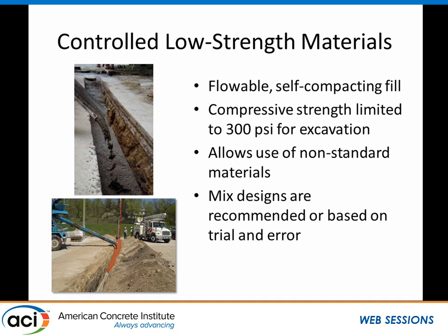And when you're trying to do this, oddly enough, the main objective is to get target strengths that are really pretty low. In fact, that's one of the hardest challenges, to keep your strengths down around 300 psi. I'm not just missing a zero there, 300 psi. And the reason you want that is to make the material excavatable.